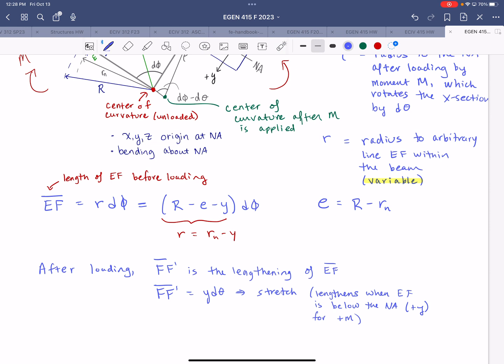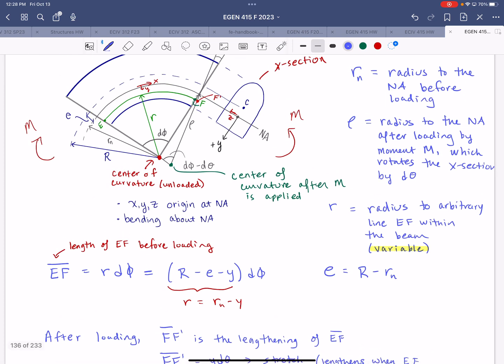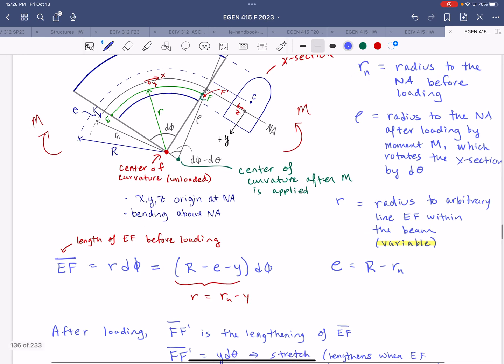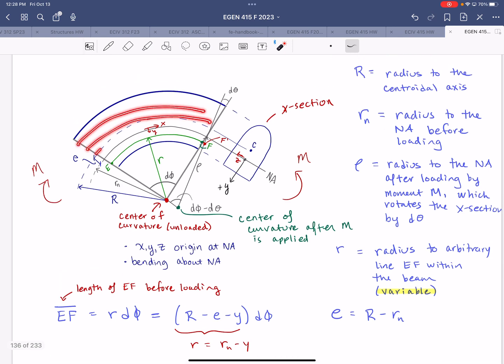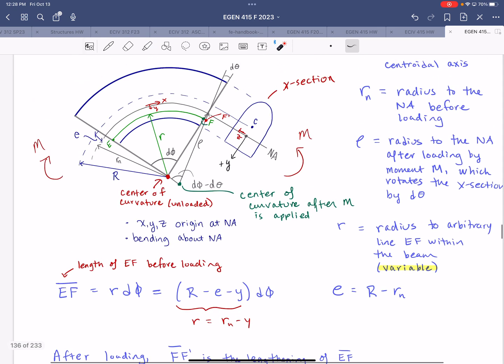Question? The assumption that plane sections remain plane means that the cross section is not deforming in its dimensions, or is that what we're saying this is doing? Saying plane sections remain plane basically says there's not going to be any horizontal slip between planes within the material. Any plane that you cut will stay in position relative to the other planes, so you won't have separation. The deformation will occur longitudinally, so the cross section itself won't be deforming. You'll see it compress there and it'll lengthen there.